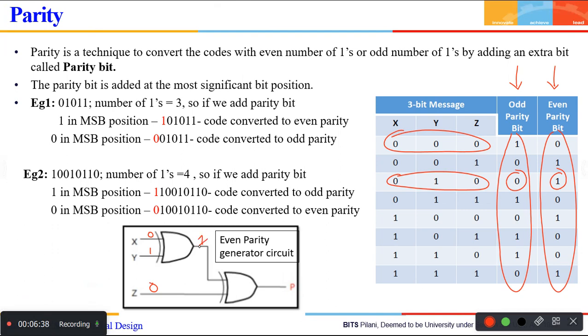What will come here is 1, right? And you can see the parity bit is going to be 1. This is called a parity bit generator. Have you understood this? Fine, okay? You can generate this for even parity; for odd parity, you can design accordingly, which will be done in the next session. And it's very simple to remember: this is the parity generator.